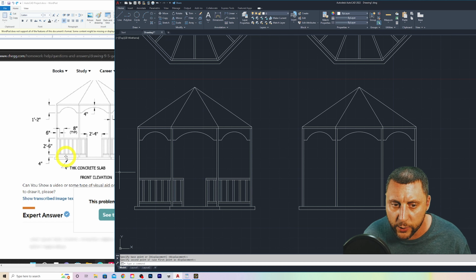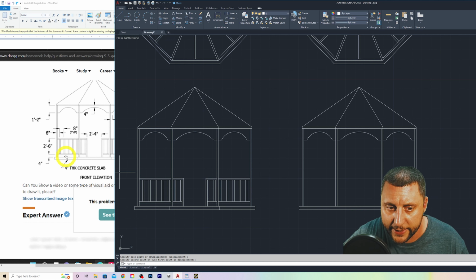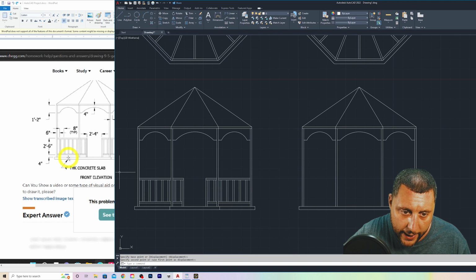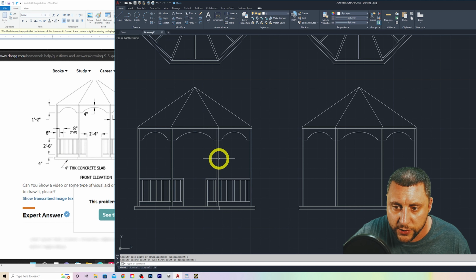Especially if this was raised and it was on a deck that's a few feet high, or like a porch, like an elevated porch or an elevated deck. They don't want anything to happen with anybody sliding out of there. So that's generally code that the ground or slab or deck or whatever it is to the bottom of the railing is about 4 inches, okay?